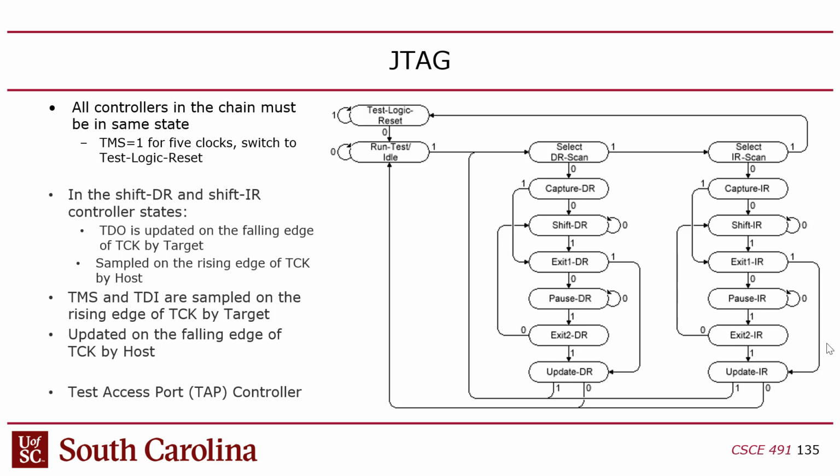So for example, if you guys noticed in 3.13, when you open up the programmer tool, it shows you a graphic of all of the 2 devices on the JTAG chain. You might be wondering, how does it know that? How does it detect that? What it's doing is it goes to the instruction register and sends a special value, which is an identification request. It says, identify yourself, slaves. And then it goes to the shift data state, and it shifts all the bits out. And from there, it can tell everything that's on that JTAG chain.